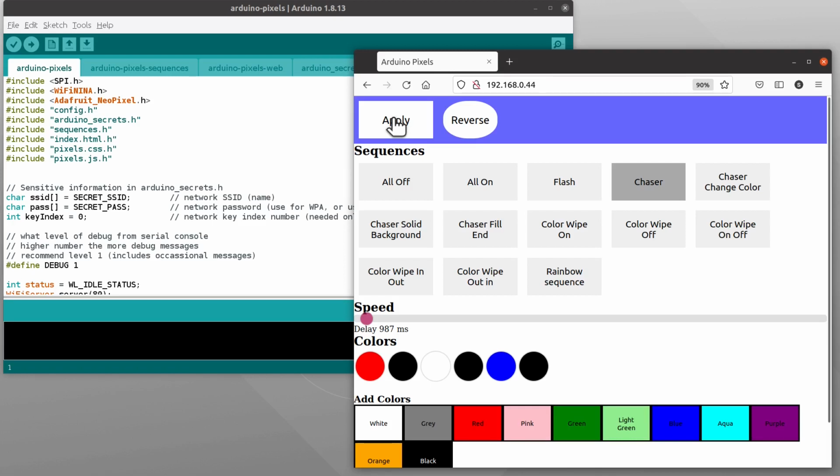The web interface provides a good way to manually control the lights, but what if you want automatic control? The way the website works is by issuing dynamic HTTP requests. So if we can imitate those in another way, then we can use that to control the LEDs without using the web interface. You can do this by working your way through the code requests and seeing how it's handled. But in this case, I'm going to show you how you can do this using the web interface and then looking at the messages sent to the Arduino.